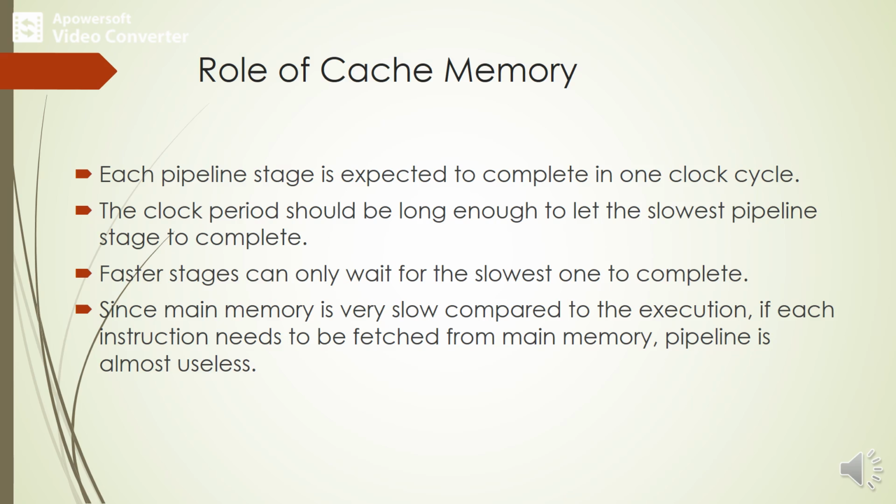A unit that completes its task early is idle for the remainder of the clock period. Hence, pipelining is most effective in improving performance if the tasks performed in different stages require about the same amount of time. We can consider a particular instruction fetch phase which is assigned one clock period.